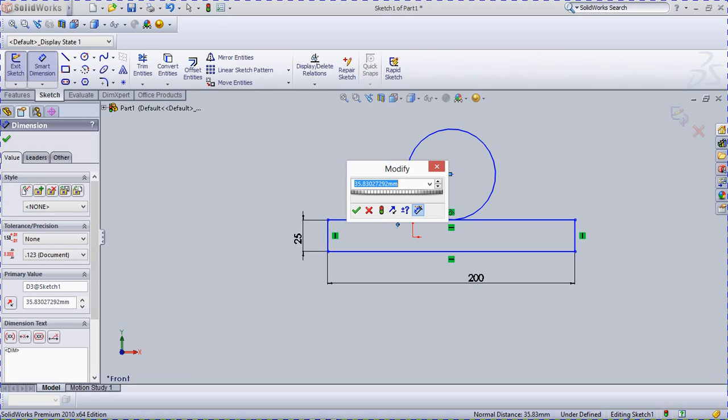Now for the bearing block, the bearing shaft will be 30, which means the outer race diameter of the bearing will be 60 mm. With a 60 mm diameter, the bearing block outer flange diameter should include the thickness we are choosing. So 25 mm plus 60 is 85 mm.